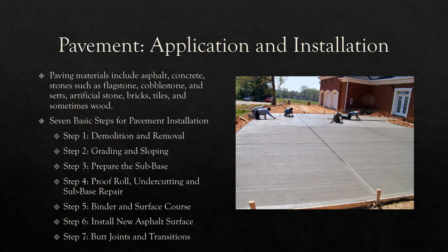Butt joints are areas where old asphalt and concrete meets new asphalt pavement. These transition areas require special attention to ensure that grading and water runoff is appropriate.